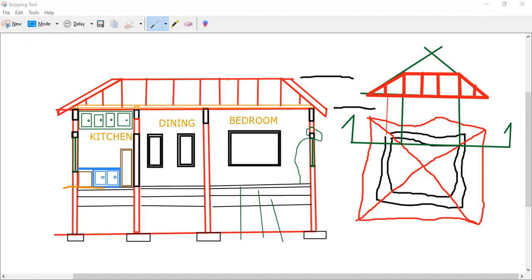So this can be done using two methods, and I want to explain another method to you, because I find the traditional method very time consuming. First you draw a vertical line, and this line should be long enough to cover the distance from the finished floor to the ring beam plus the depth of your foundation. So typically you'd make this roughly 3,000 plus one, probably 4,000 is good.